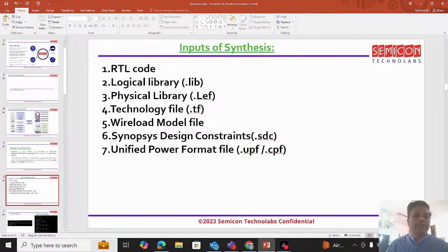However, in the timing constraints file, we give pessimistic max transition values so that it will reduce the cell delays and more levels of logic can be placed in the given clock period, right? Similarly, we can increase the clock frequency as well by reducing the clock period, right? These are some applications of going with pessimistic transitions. Similarly, electromigration violations also will come down if you go with pessimistic transition values.